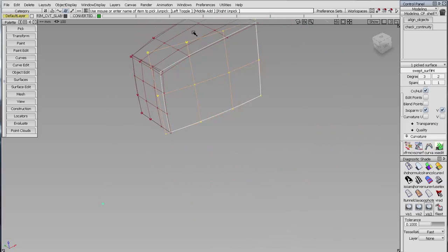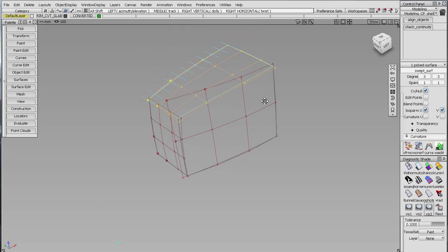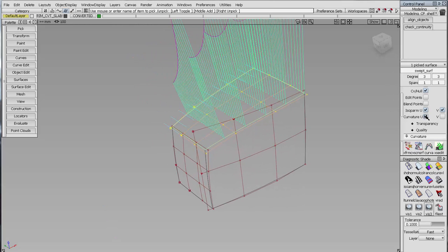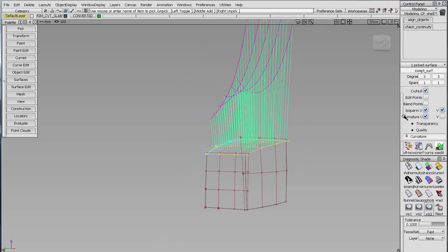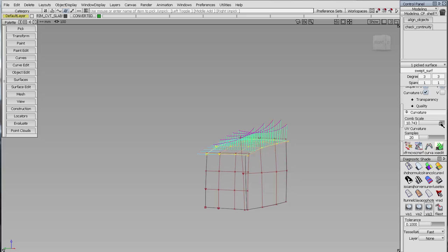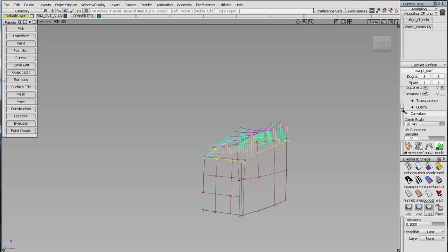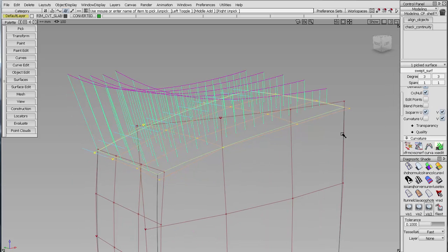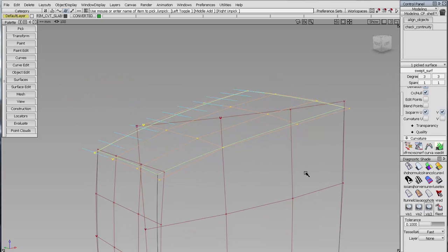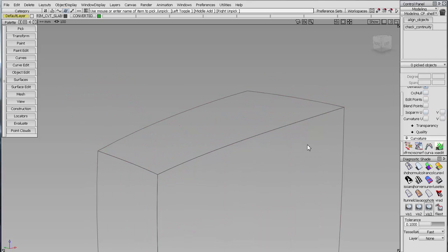If we switch now to this surface and we look, we have kind of an accelerating curvature at the outboard side, right? And then if we look in the opposite direction, we've got pretty nice acceleration at the front side. So two good surfaces. Well, the issue that you can find is two good surfaces may not produce a good intersection.